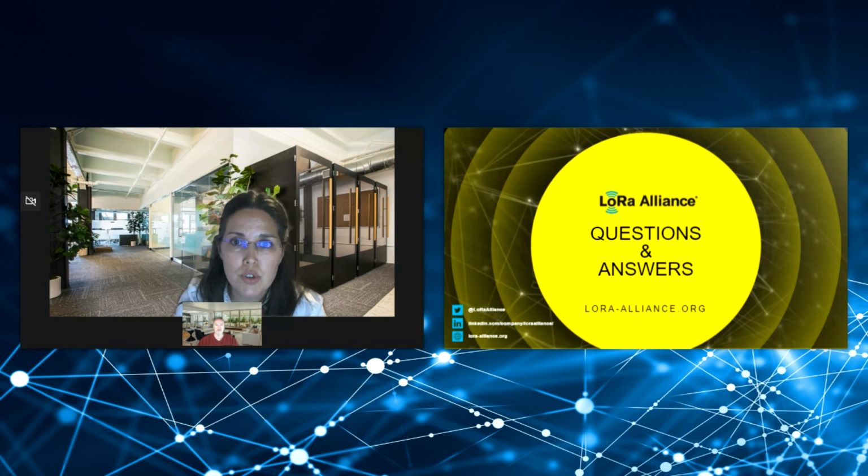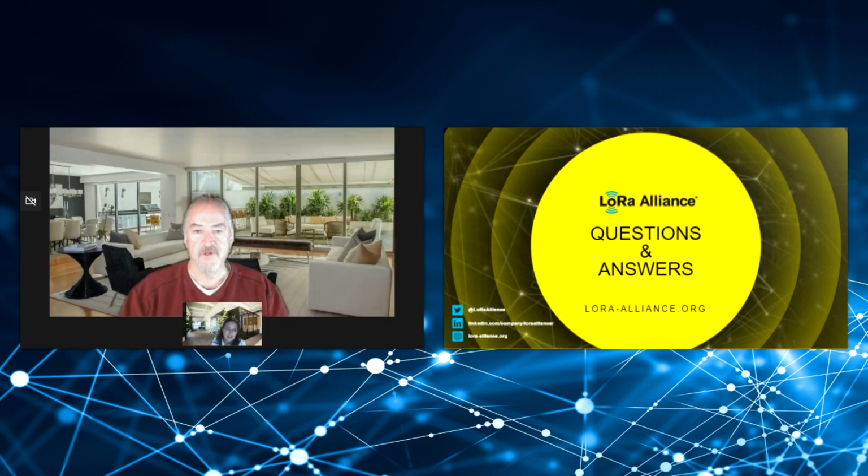The end device does not require the certification protocol because the LCTT will not control it. It's quite important to configure the end device with an uplink periodicity, just to be able to run the test quickly. It's basically a truncated version of the test that a new device has to go through.